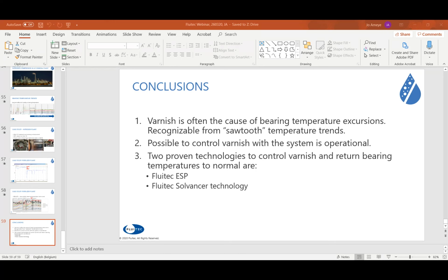Okay, I've got one other one, which is something that I think we at Fluitec are hearing more and more often now. A customer is using one of our filter systems, ESP systems, and if he stops using it, he's noticing that his filters are starting to block, but he's not necessarily seeing a rapid rise in MPC. His MPC is remaining low, but he's getting blocked filters.